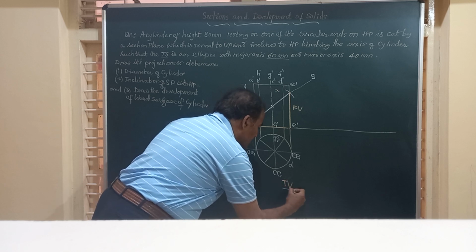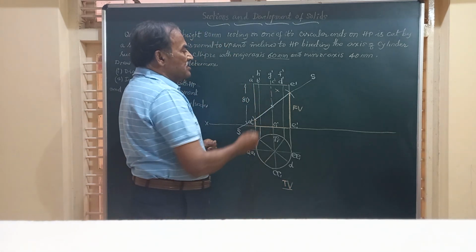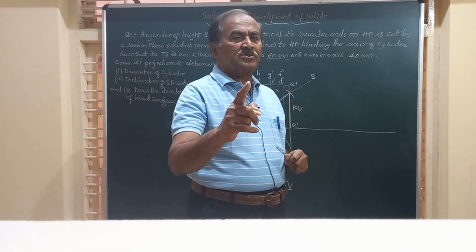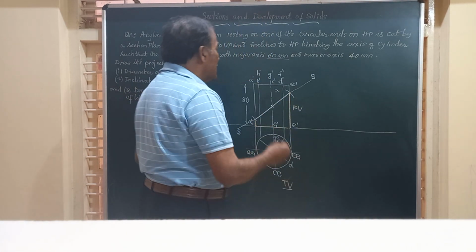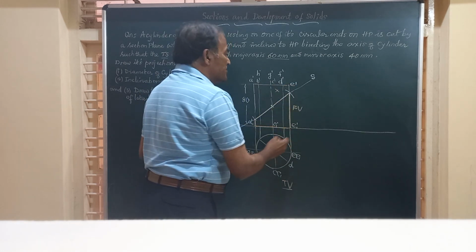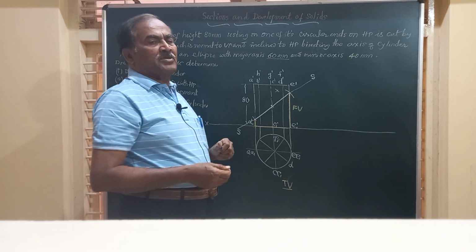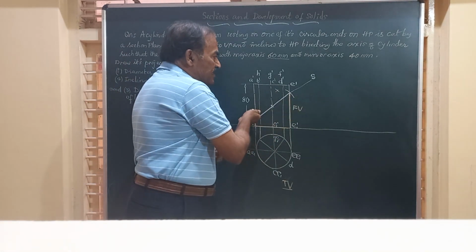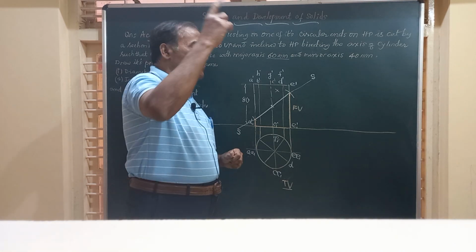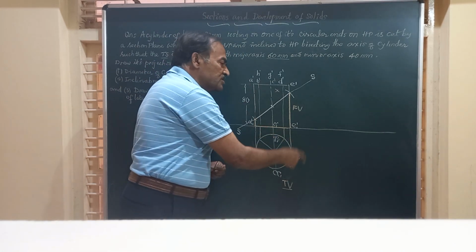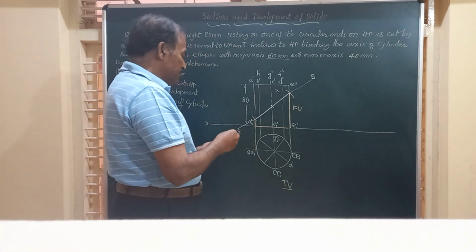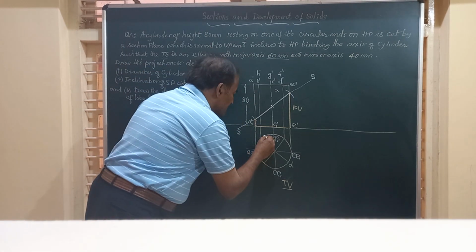And friends, remember, whenever any of the prisms, cubes and cylinders are cut in between the top surface and the bottom surface by any section plane, either horizontal or inclined to HP, then the complete top view, whatever you see of the solid, is totally section, because you can just write like this.